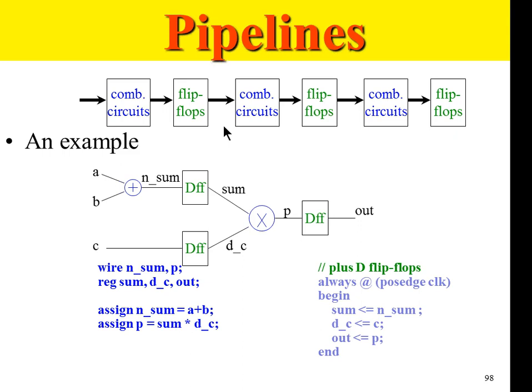Let's say I want to work on a 100 megahertz design. 100 megahertz is the clock cycle. If you convert it to time, it will be 10 nanoseconds per 100 megahertz. So when I say my design is supposed to work at 100 megahertz, let's assume there are 100 different logical paths in the design. Different paths means there is various logic defined. Each of the paths has to meet that 100 megahertz requirement, or 10 nanosecond requirement.